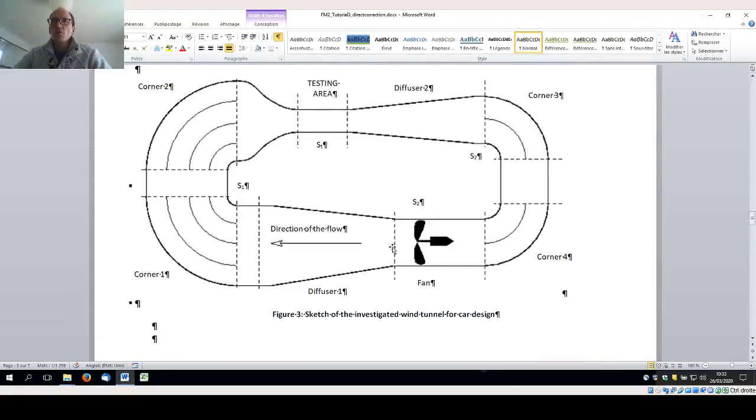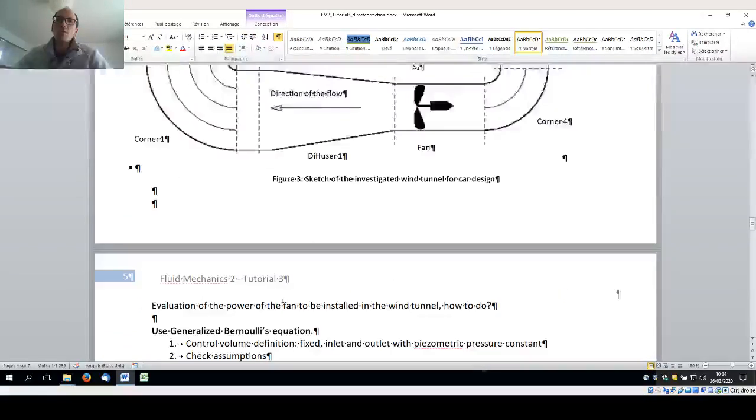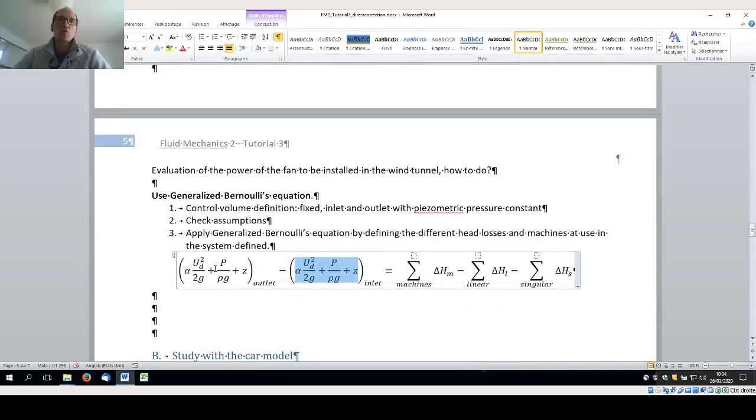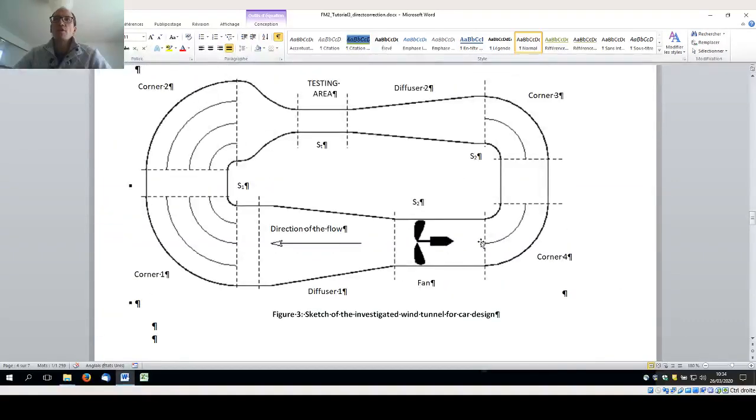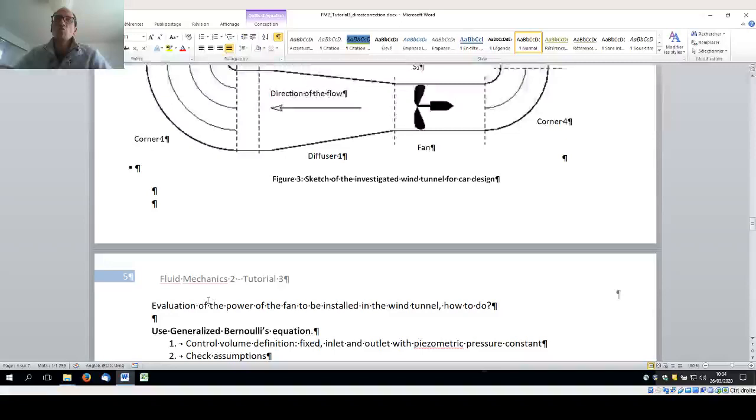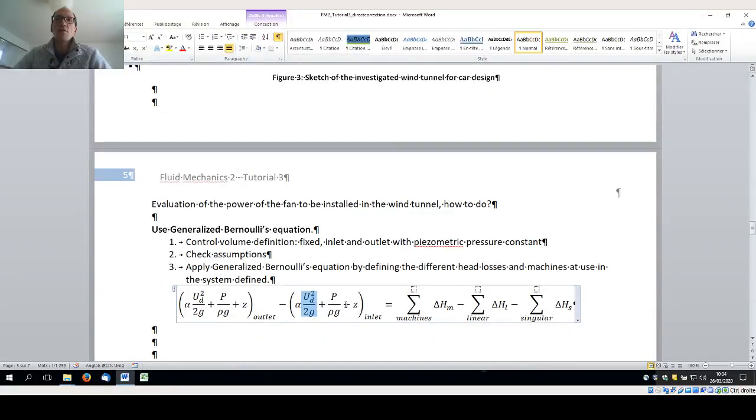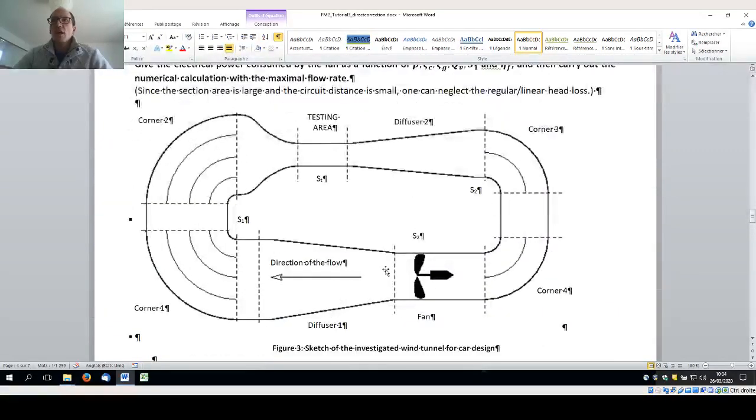That's for sure possible, but in those sections before and after the fan, since you know the flow rate, you know the mean flow velocity UD. So you know this term in inlet and outlet. The vertical location Z, you also know in inlet and outlet. But the problem is the pressure. I do not have any information on pressure in inlet and outlet here, so I will not be able to evaluate the left-hand side of the equation.